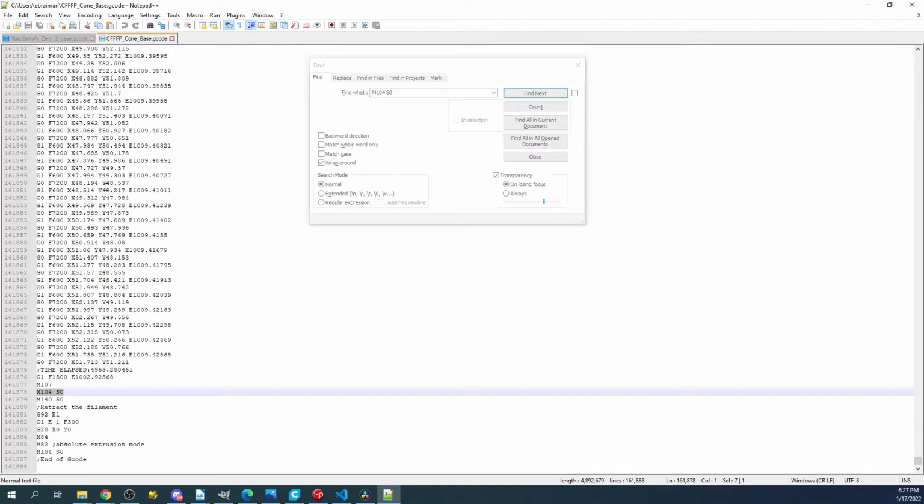Let me see if I can find it real quick. So here's the extruder. I'm going to disconnect the power for a second and put it where you can see it. And if you look at the bed, if the power doesn't go out, there's an extruder right here. Essentially it takes two inputs. So on this one I made a mistake. I have actually two of these. So I essentially have to clean out the actual material, but I forgot to put the PTFE all the way down into here.